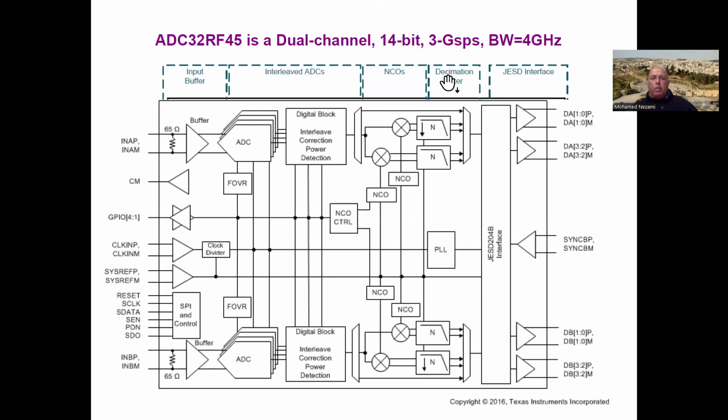So we need to decimate. You've got decimation and filtering to do that. Right after that, you're ready to move your digitized samples to the next stage, which is your digital demodulation, decoding, deciphering, packetizing, and so on.